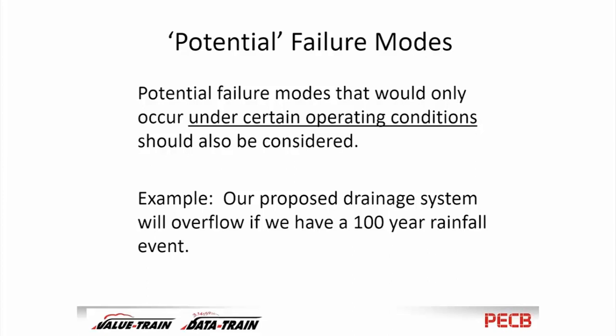It's pretty typical in any sort of manufacturing plant or a chemical plant where they have tanks that store hazardous material to build a dike around the tank. You essentially build a wall all the way around the tank so that if the tank were to fail and all that liquid were to come out, the wall is big enough to hold the volume of material that's in the tank. So that's the purpose of that thing.